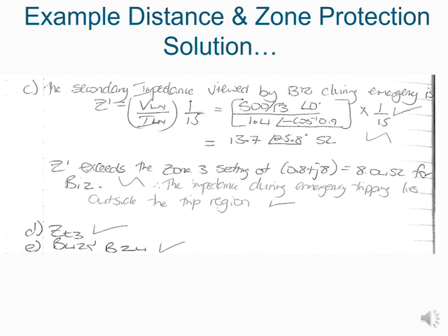If your emergency scenario gave you an impedance that was less than the zone 3 reach, which is the 8.04, let's say you ended up with 7.95 ohms, then unfortunately it would mean that in an emergency scenario, your zone 3 would be able to take out your line.